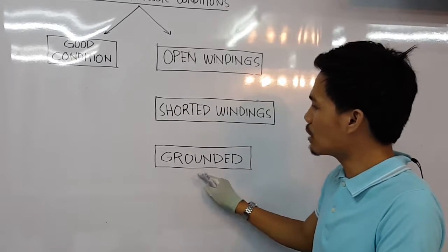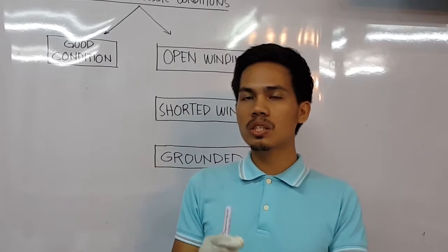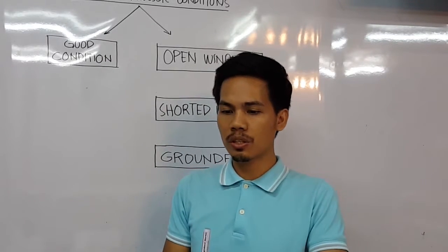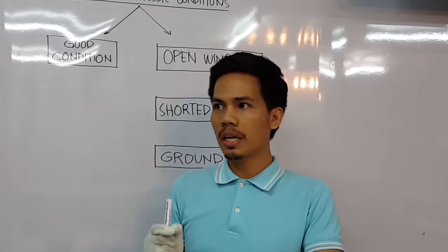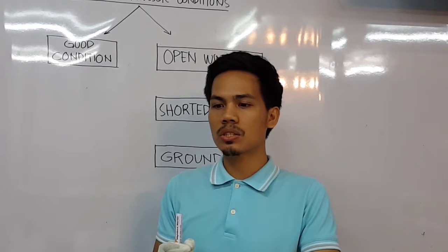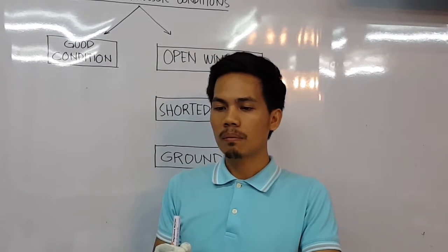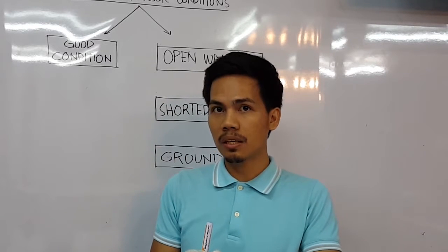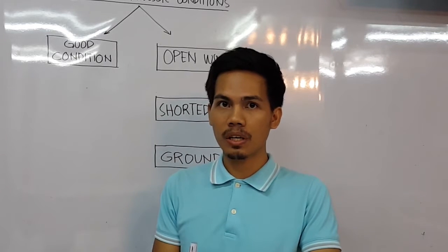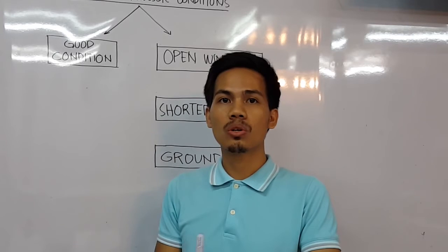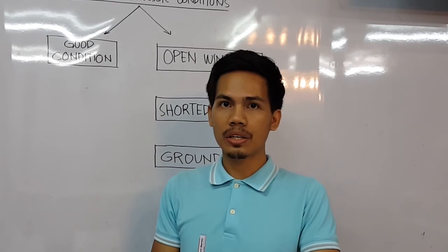Then, lastly, the grounded. For grounded, this is a special case of a motor compressor. When you test the common, running, and starting terminals against its body, it has a reading, regardless of whether it is 0 ohms or a higher resistance.